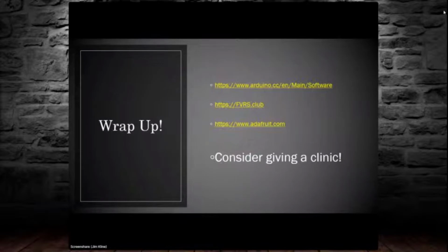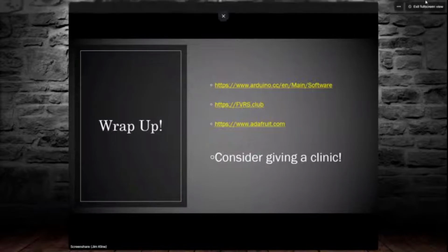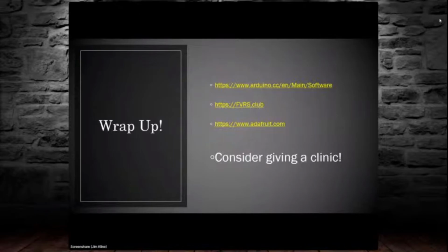So I'm going to wrap up today with a short video of the working traffic light using LEDs, but not discrete LEDs that we just wrote a sketch for. These are very special LEDs known as NeoPixels, and they are wired in series and only one pin is needed from the Arduino to operate them. The program flow is the same as the sketch that we just wrote, but the activation of the LEDs takes a different form than the pin mode command that we've been using.